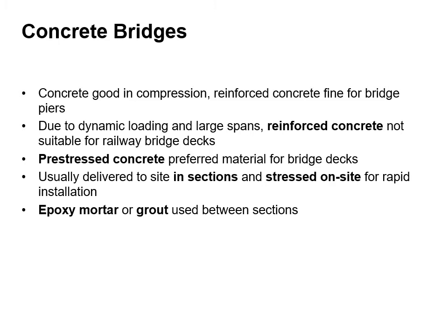Pre-stressed concrete is a preferred material for bridge decks. It's usually delivered to site in sections and stressed on site for rapid installation. And typically there'll be an epoxy mortar or grout used between the sections.